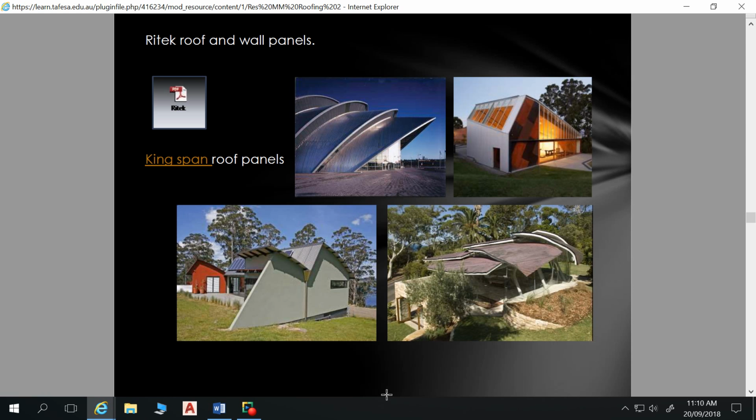Whereas with this stuff, your insulation is continuous. So yes, it might only be 2.5, but nowhere along that wall is there any thermal conductivity. So although it's only 2.5, it actually performs really well. And that's an issue with the National Construction Code way testing is carried out, etc.